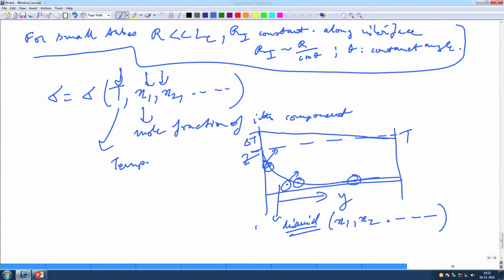So when you determine the surface tension of a mixture, that will also be different because it is a mixture of different species, right. So the moment you have this kind of multi-component system, along the interface there will be a lot of variation in surface tension as well. There can be a variation in temperature, there can be a variation in species concentration. All these will lead to a surface tension gradient, basically. So there is what we call a d sigma by dT or a d sigma by dx, dy, whatever you call it. There are terms like this.